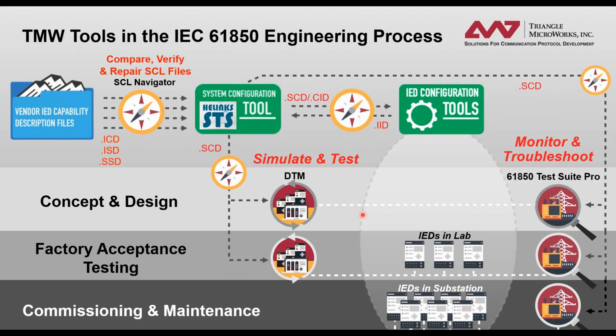61850 brings a lot of concepts to the design of power systems that are additional to what previous wireline protocols have brought. Some of that is the semantic data model, a very important piece of the pie that allows us to communicate what the data is in the devices in addition to the raw numbers. But it also standardizes the design process. And that's what we're going to talk about today. The design process is based around system configuration language, which allows tools and devices from different vendors to exchange information.